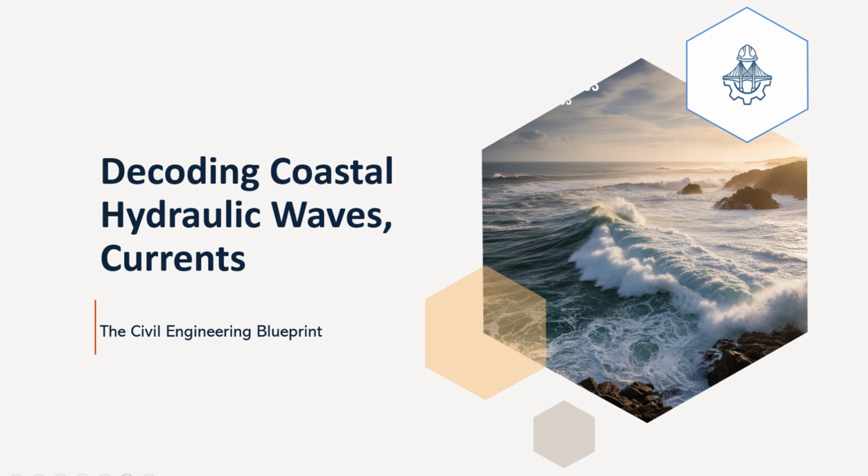Okay, now let's connect this energy concept back to wave shoaling. But this time, let's look at the quantitative analysis. As we discussed earlier, waves undergo profound changes as they enter shallower water, particularly in height. A key assumption, and often a very good one away from breaking in shoaling calculations, is the principle of energy conservation between wave rays or orthogonals, lines perpendicular to wave crests. We assume that, barring energy loss to friction or breaking, the wave power P remains constant as the wave travels from deep to shallow water between two adjacent orthogonals.